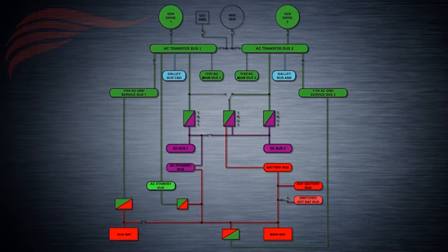Notice that the AC standby bus is partly AC powered only by AC transfer bus 1, but it also has a part which is powered by AC current derived from the DC electric system. DC to AC conversion is achieved with an inverter and will also be discussed later on.